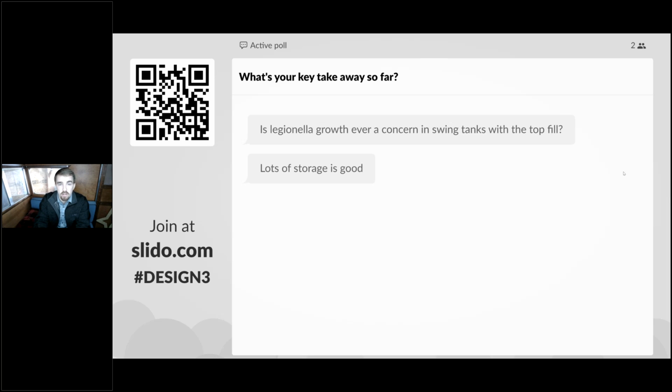In terms of the controls temperature, that's a little different because we're talking about that stratified storage where you see a significant drop in temperature as soon as that cool water works its way up to the temperature sensor. So even though the storage will sit at 150, we might turn the heat pump on when that temperature sensor drops down to, say, 120. So there's a really strong buffer there to make sure that that cold water has actually made it up to that temperature sensor. So that's a great point though to bring up.